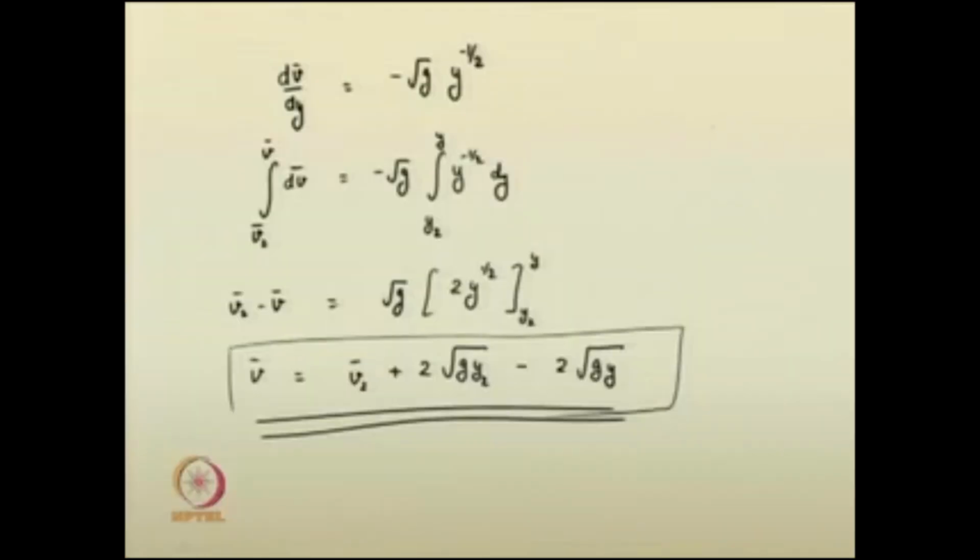Or you can interpret it as the condition at which the beginning of the wave arises. So, you cannot say it is simply the height of the sluice gate, it is the height at which the wave starts propagating. So, that is y1. Within those limits, y2 is a known quantity, and based on that V can be evaluated.